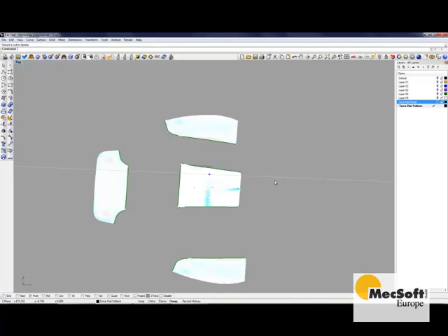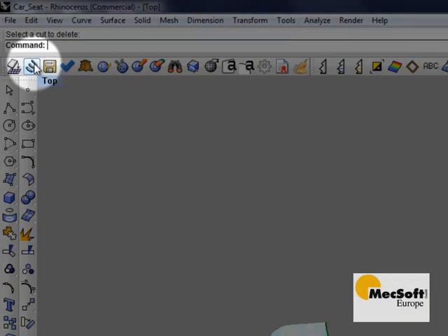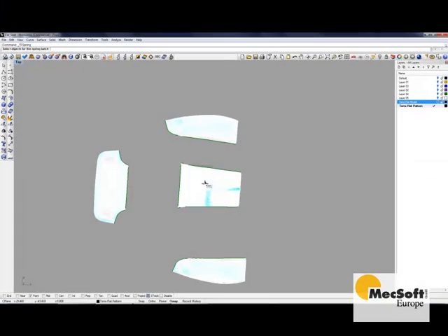So we have those pieces put back together. Once I do that though, I want to go back in and I want to spring this piece, because you can see there's a little bit of stress that's been added to this piece when I've sewn them all together, which would make sense. So I'll click this, hit enter on my keyboard, and I'll simply go through and reflatten that piece. And now we have a piece that's ready to go out for cutting.